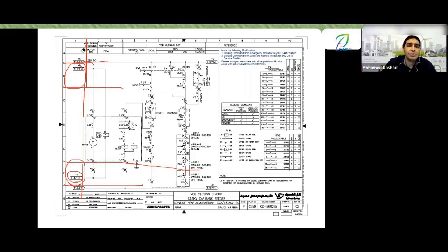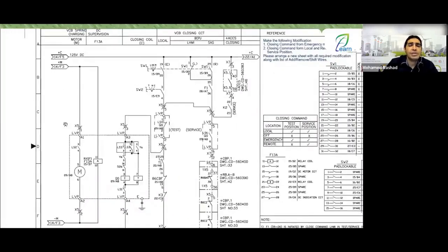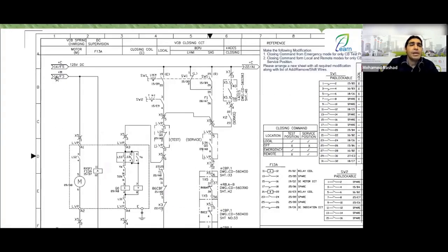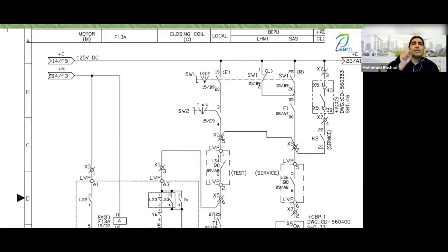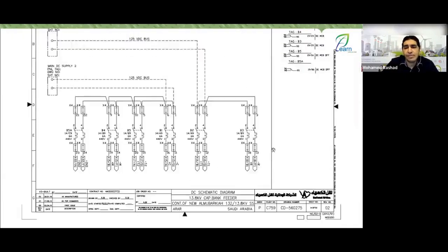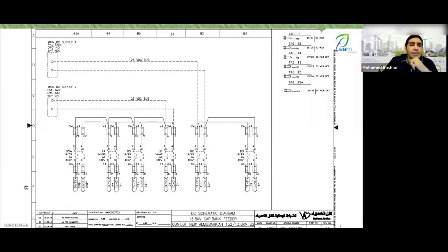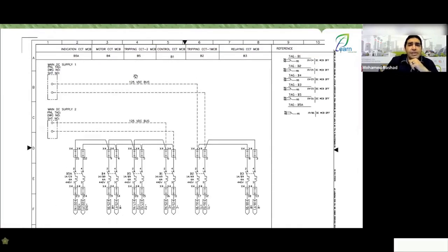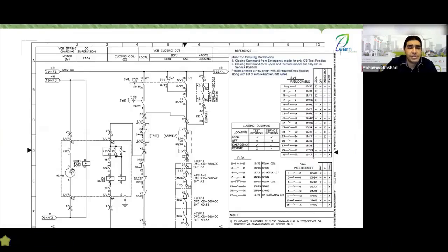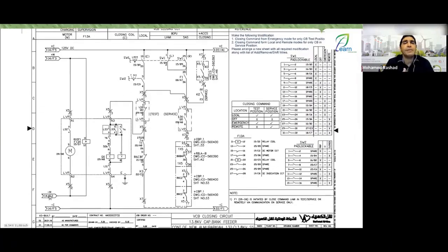So indeed it led me to the cross reference or the grid. I have to know which page it is going to and where it is located on which page. So when I came here, I found it telling me that this place is coming to you from page 14, F3. If you took a step back to page 14 F3, here's the F going this way, and here's the 3 coming down from above like this. And here the F and the 3 intersect. So you actually find your plus M and minus M, the same thing coming from F3.